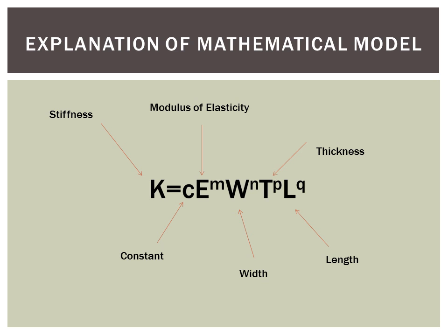By using this equation, you're basically able to find out the stiffness of any type of material, and you just plug in the numbers that correspond to that material and the different parameters. For instance, if you have aluminum, you plug in the modulus of elasticity for aluminum, the width, the thickness, and the length of aluminum, and you'll be able to find out the stiffness of that material.